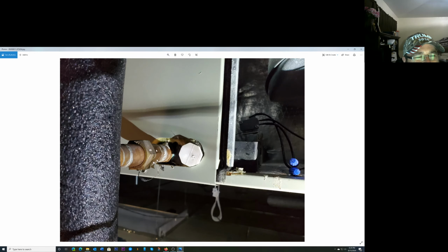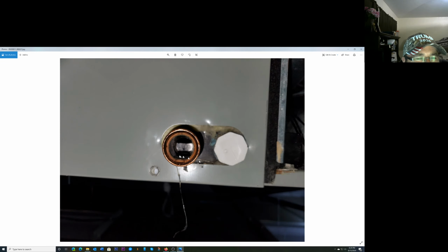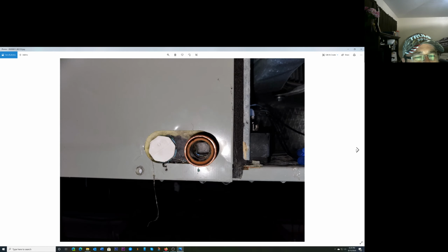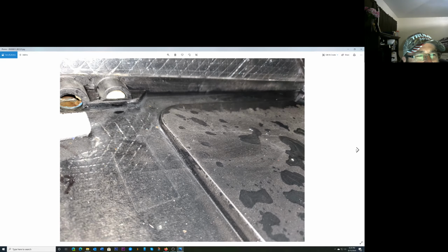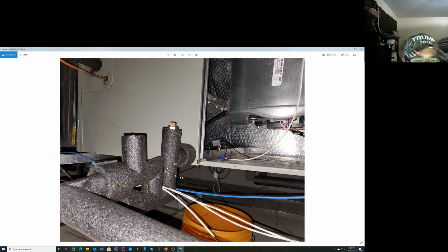I've got to put that chat window in there when I figure this out, guys. But so right here, that's how high the water was, and the water wasn't going out the primary because they had the pipes reversed. They had the drain pipe here when it needed to be here. So I pulled the pipe out. There's your little knock-out on your pan. So water had to go up here. By then the water's this high, and the blower's just sucking it off the top. So I just reversed them and reconnected it like it's supposed to be.